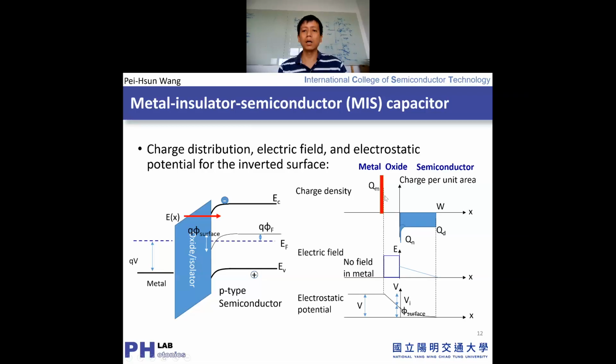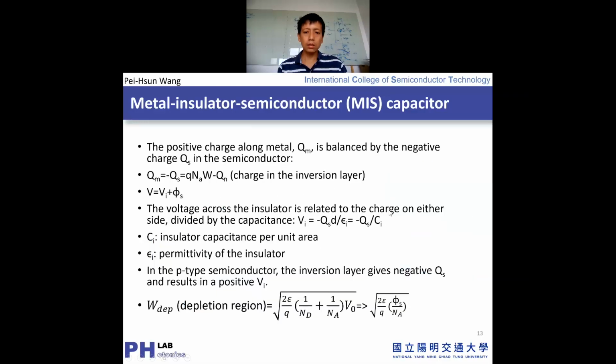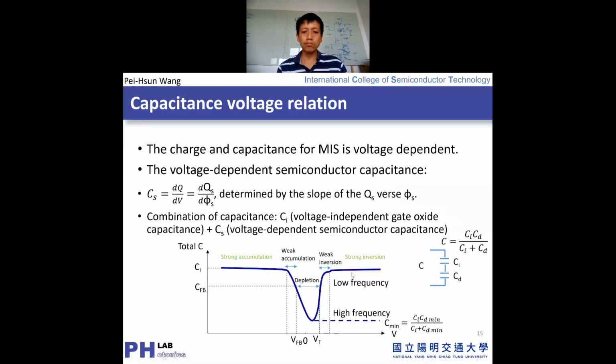So it works again like a capacitor separated by an insulator or oxide, and the capacitance will be proportional to epsilon A over D. Okay. So under this condition, you go back to the original capacitance value. So it will go down because we do not have any charge around the depletion region, and then go up for both the inversion layer and also strong accumulation. But if you look at some interesting case, you get two different charge accumulations or capacitances. There will be a combination.